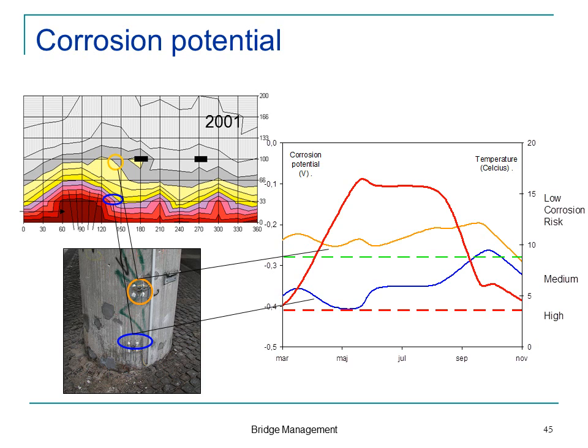We could check the corrosion potential, and we could do it with, say, sensors to see, are there any variations of these over the year? Do we see, from one year up to November, some variations of the potentials, but this down here would be a high risk of corrosion, this would be medium, this would be low, so the risk of corrosion seems to be fairly constant, even if temperature varies quite a lot.